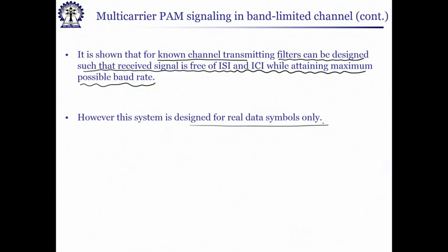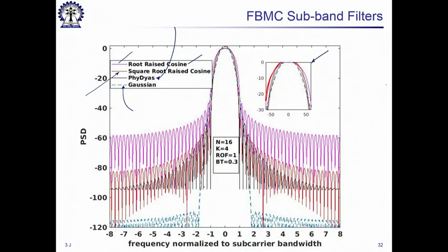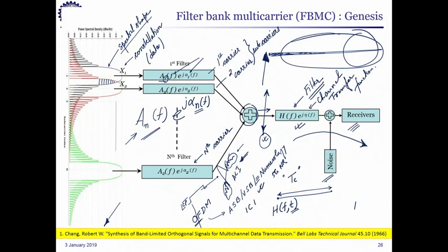So, what we summarize is that if we want multicarrier mechanisms which are not OFDM, but some other ones, and the special property that we want in them is good out of band signals, that means less adjacent channel interference, then we have to go for structures which are usually termed as filter bank multicarrier. The genesis is given in this particular reference, where each subcarrier is filtered,